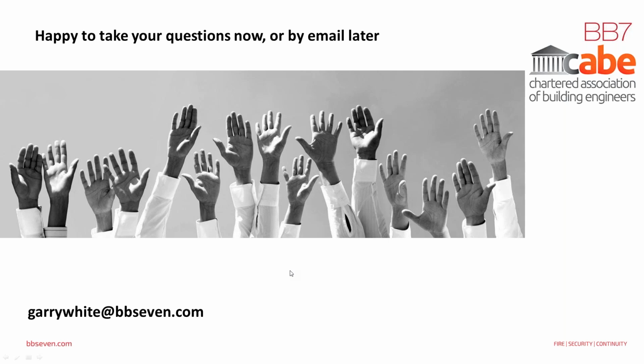Right, okay, thank you. Now, I've had a load of you come back to me with regard to the radon barrier. So if it's okay, Gary, we'll just go back to that question if you're able to answer it. Everybody's confirming that a radon barrier would be a damp-proof course. A radon barrier is a membrane normally installed on the ground floor to prevent radon gas from entering the property. So going back to the original question, should cavity barriers basically extend below that damp-proof course level?